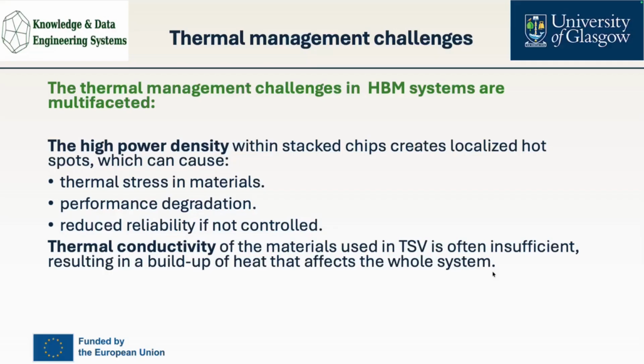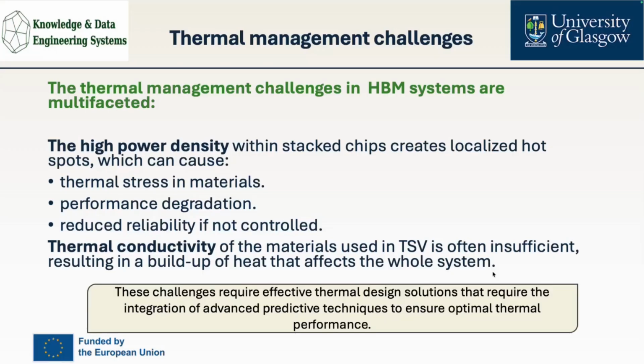Also, we could have another problem, which is the thermal conductivity of the material used in building the TSV. It's often insufficient, resulting in a buildup of heat that affects the whole system performance. So these challenges require efficient thermal design solutions that require the integration of advanced predictive technology to ensure optimal thermal performance.